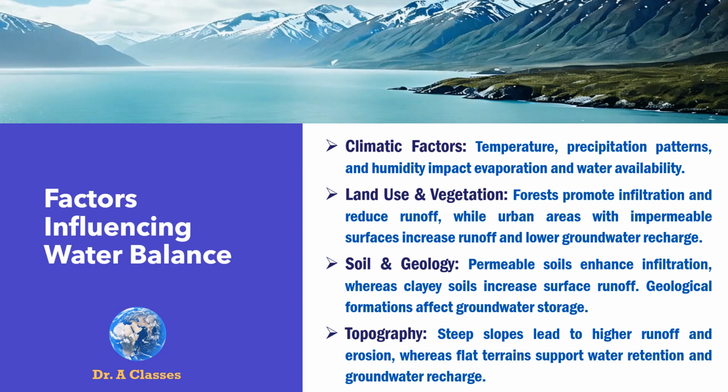Factors influencing water balance. Climatic factors: temperature, precipitation pattern, and humidity impact evaporation and water availability. Land use and vegetation: forests promote infiltration and reduce runoff, while urban areas with impermeable surfaces increase runoff and lower groundwater recharge.